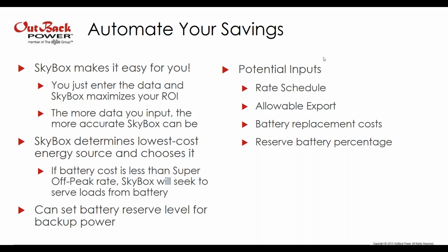So some of the potential inputs, you'd enter the rate schedule, whether or not export is allowable at that particular location, what your battery replacement cost is as the installer. What is the cost for you to do a truck roll at the end of the natural life of those batteries years down the road? And then finally, how much of the battery, on a percentage basis, should be reserved for backup power.